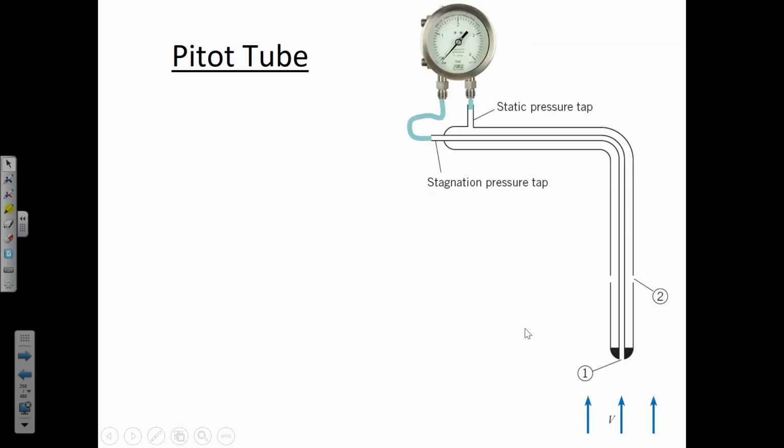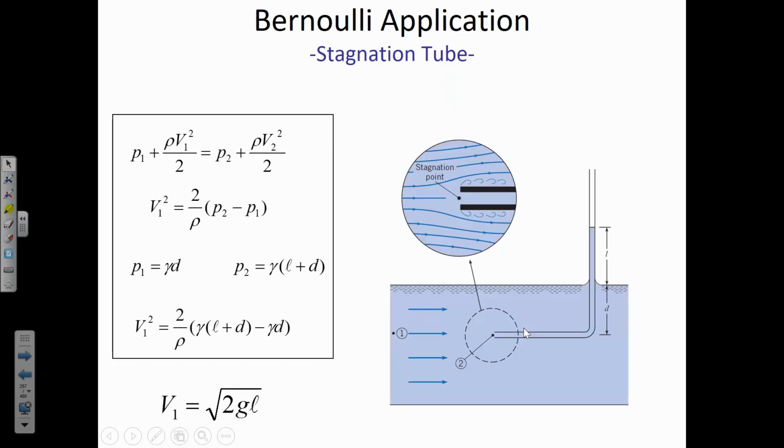All right. So the next level, taking a stagnation tube to a more sophisticated place that is more broadly applicable out in the field, is a Pitot tube. Now the weakness with the stagnation tube is that this device really only works if you're measuring the flow of a liquid.